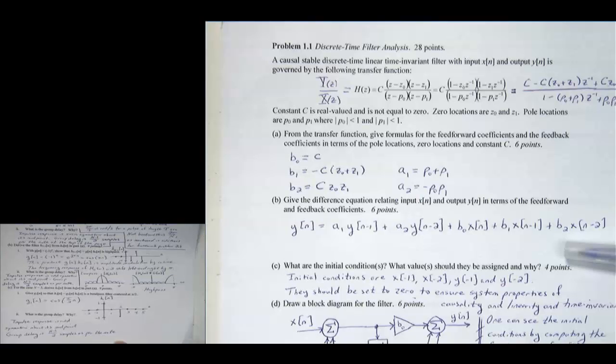I'll use that impulse response for g1[n], which works because h0[n] is already finite in duration. So if I multiply an IIR response with an FIR in the time domain, I'm only as long as h0[n]. So that was good insight. Really good insight. I hadn't thought about that approach.